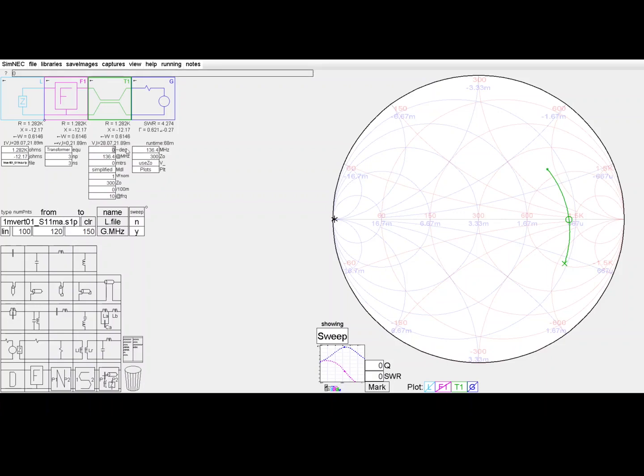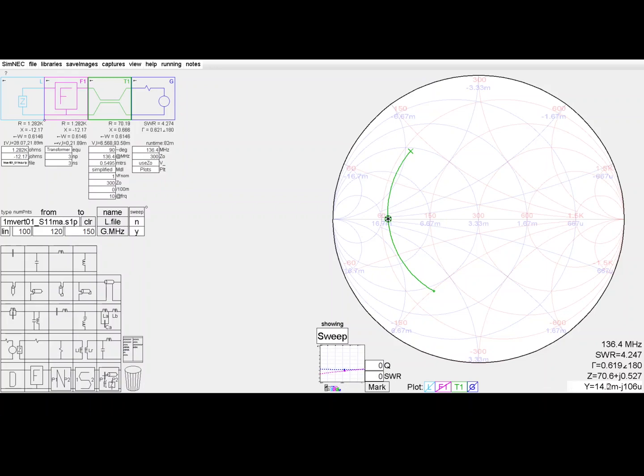And if I just put 90 degrees in there, that takes us all the way back over here. And that's interesting. This impedance is looking more interesting. That's looking like 70 ohms. By adjusting the ZO, we can move this in and out. Go back to a 50 ohm reference, you'll realise that it's not rotating about the chart centre, but it's rotating about 300 ohms, which is just over here. And it's not so easy to see geometrically when it's not the chart centre.